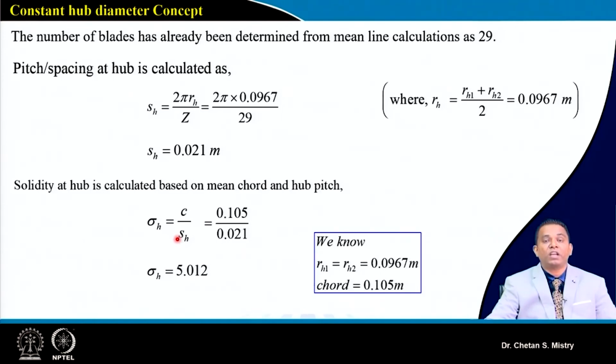If we are changing our chord length, accordingly we will be having a change in our camber angle. So there are many iterations people are doing in order to manage the flow properly near the hub region. So they will be having variation of chord from hub to tip. For many industrial designs, maybe industrial compressors as well as industrial fans, you can see this kind of configuration.